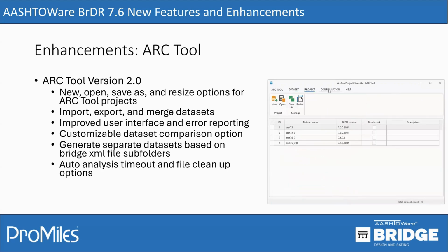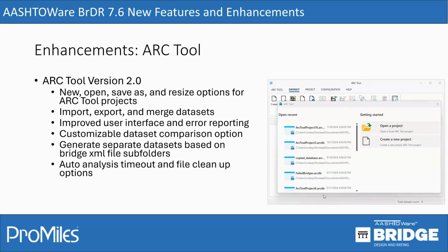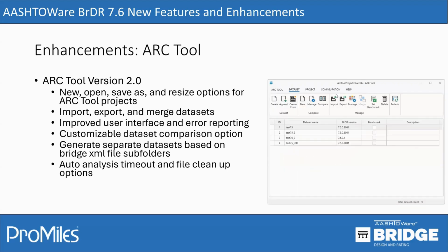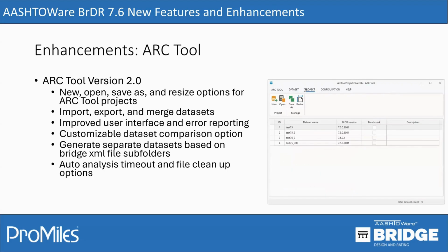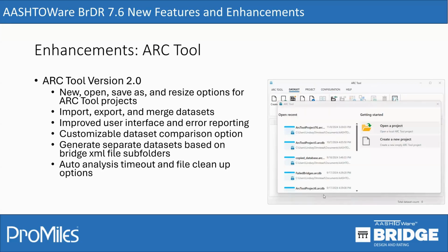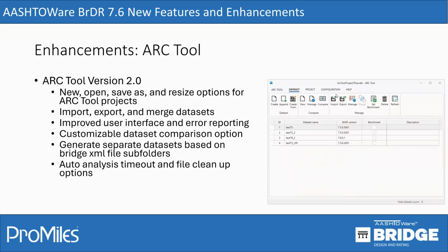You can also set up multiple folders in your file explorer and then create separate data sets based on this folder structure in one window if you call create data sets. That's a nice feature if you don't want to click on multiple folders and create data sets per folder. Also, if a bridge is running for a long time and you would like to skip it and move on to the next one, there is an auto analysis timeout feature, which you can access from the settings window.